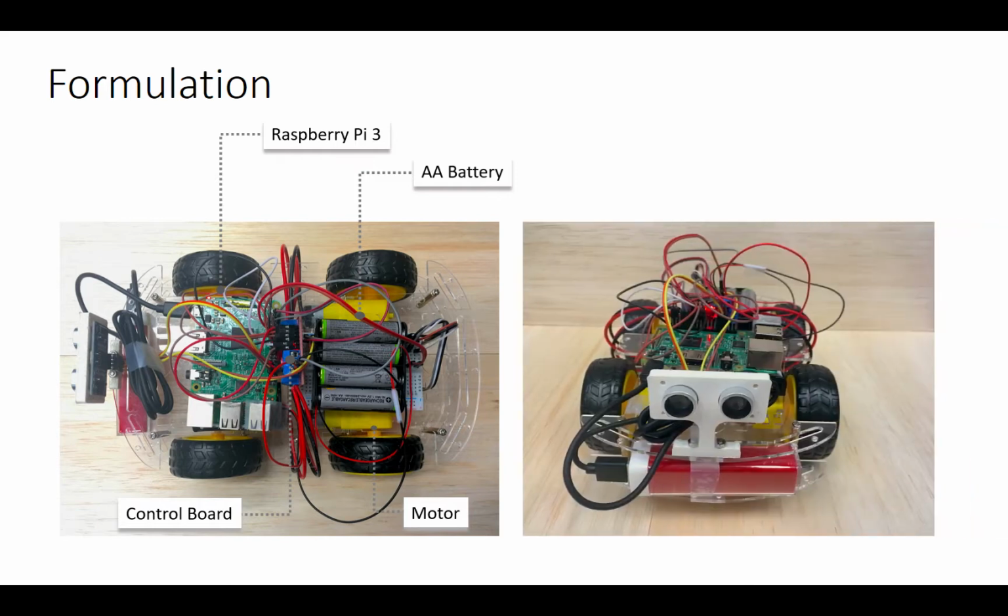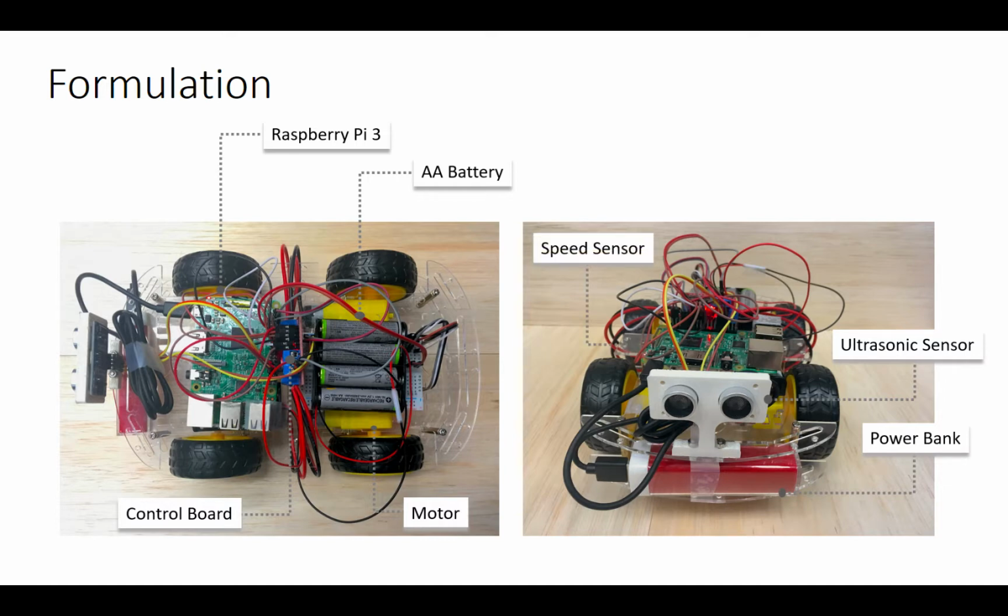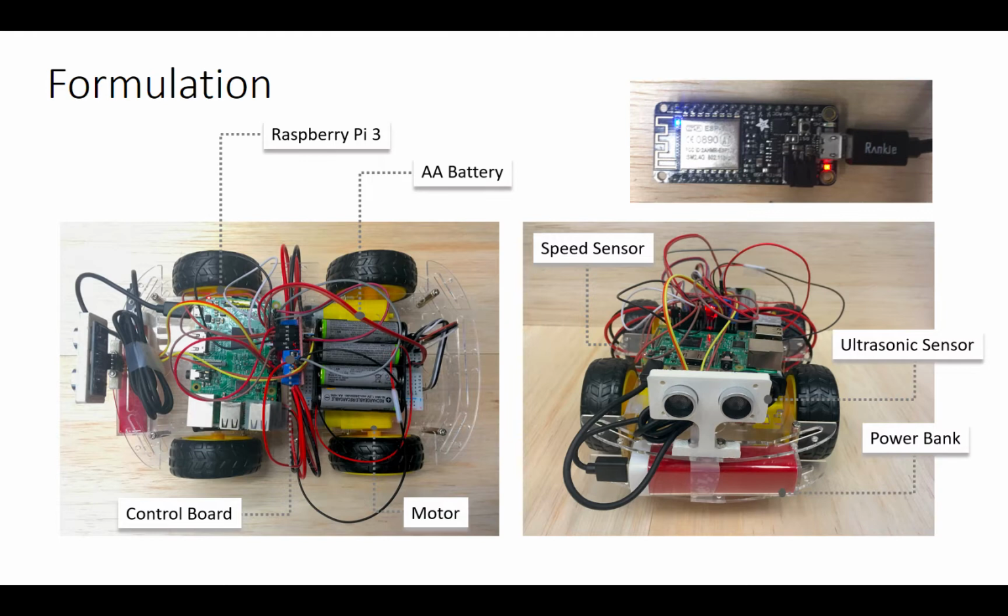The picture on the left side is the front view of the IoT car. The ultrasonic sensor is in the front, and it will detect the distance to the board and then calculate the distance to the traffic light. In the bottom is the power button to power up the Raspberry Pi. There are 2 Hall effect speed sensors to sense the speed of the wheel, and we could use them to calculate the travel speed and distance. We use the built-in light on the hazard board to illustrate the traffic lights. Here, note that the blue light actually represents the green signal.